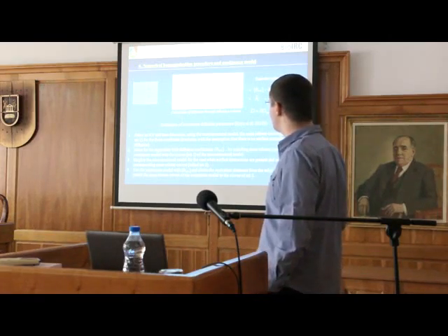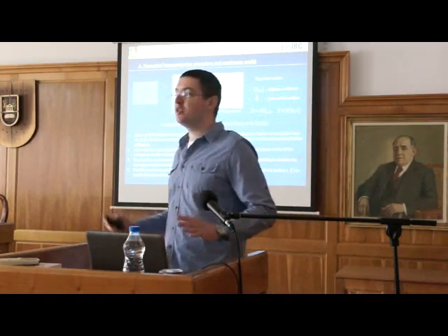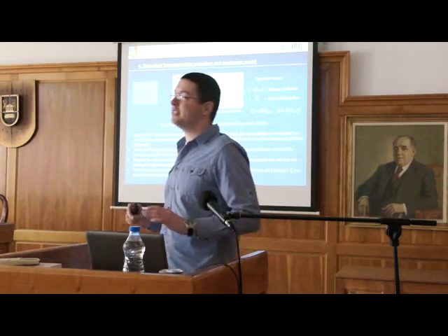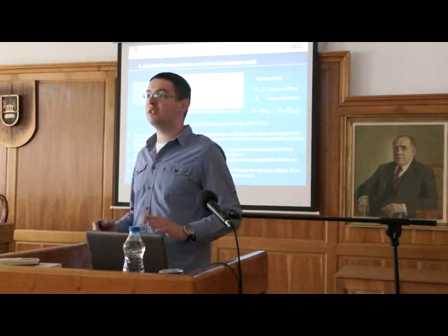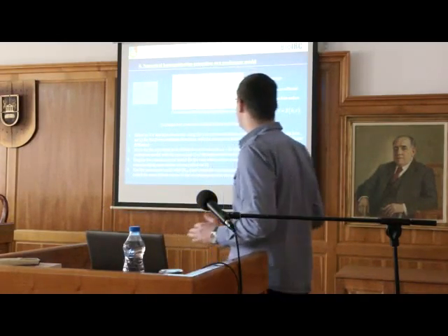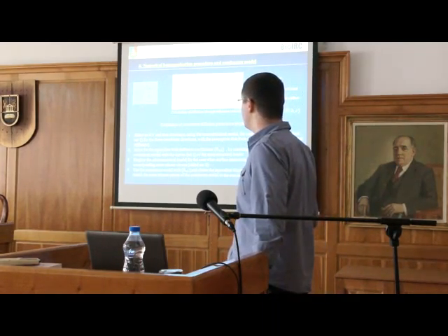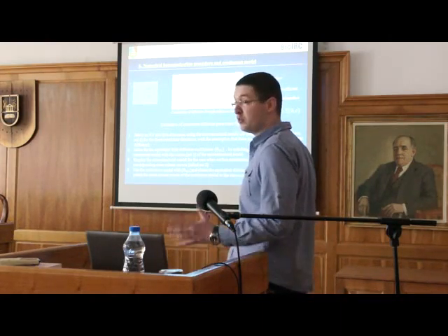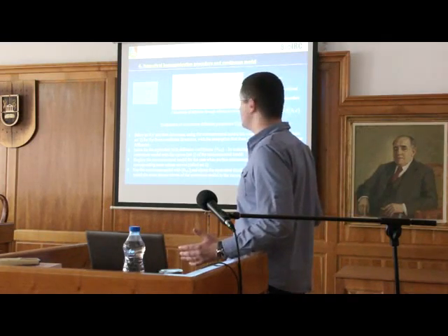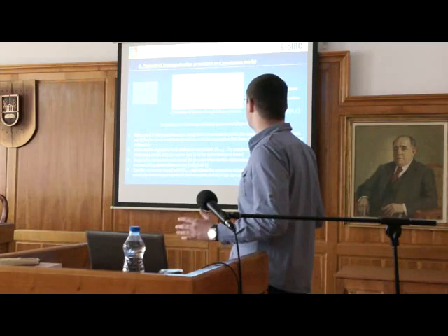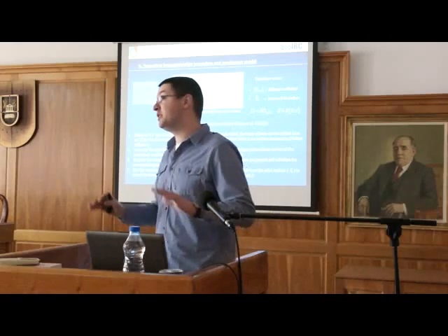This is that homogenization procedure I was talking about. And what is the point? We have a microstructural model, which is a real model with fibers. We want to replace that microstructural model with a homogeneous model. Homogeneous means that there are no fibers in that reference volume. So we started from this equation, which says that characteristics of the process have to be the same for both models. We have to get the same mass release curves for both models, and that is validation that those two models are basically the same.